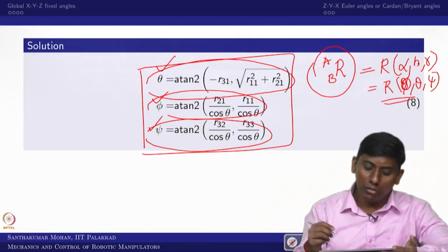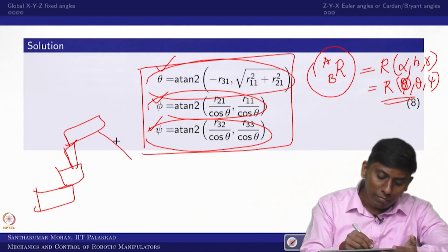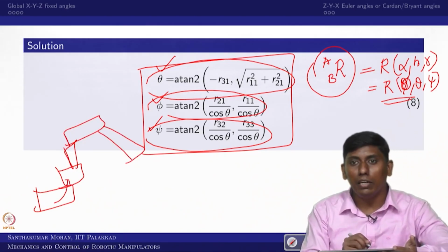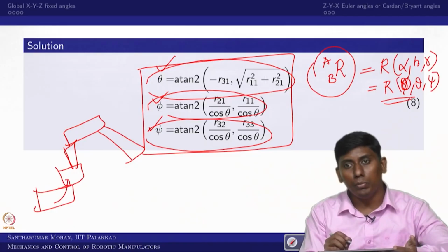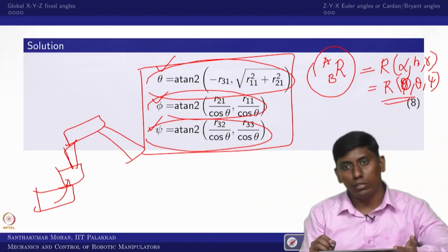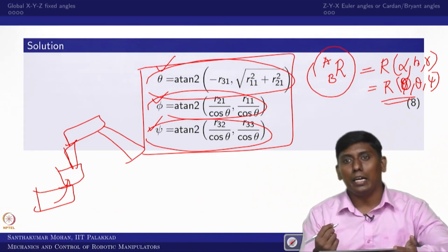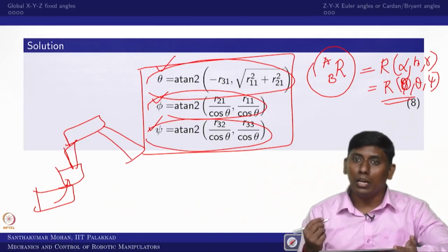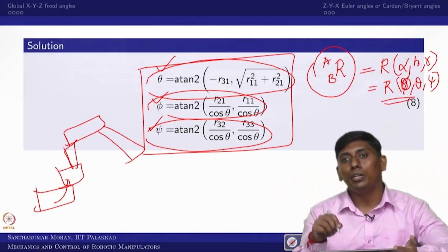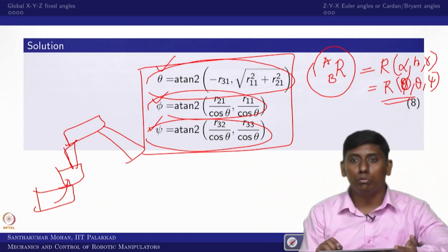However, if you are using a multi-body system, for example a manipulator having several bodies, then one body to another body you would have 3 translational and 3 orientational pieces of information. The translational information is very straightforward because it is given as a position vector. However, the orientational information is not straightforward. You cannot directly write alpha, beta, gamma. You have to get some rotation matrix. So for finding the rotation matrix, how will you get this alpha, beta, gamma? This is one of the questions, and there is no straightforward technique to do this.